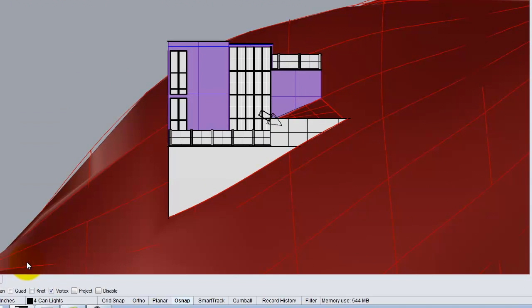Now, as part of this export, I'd like to have some contour lines that help represent the terrain. Before I actually do my Make 2D, which is what we're getting to, I'm going to create a set of Z contours that are just part of this export. This has nothing to do with creating a physical model, so the interval, remember we used to use that chart to pick what the interval was, doesn't matter for what I'm doing here. I'll pick, say, maybe 2 feet, and I'll contour.